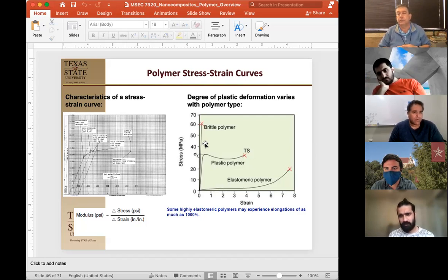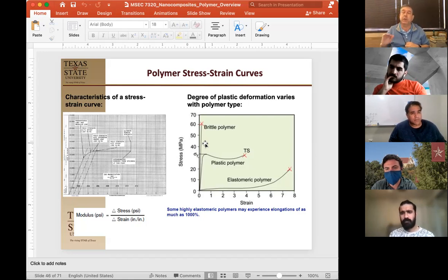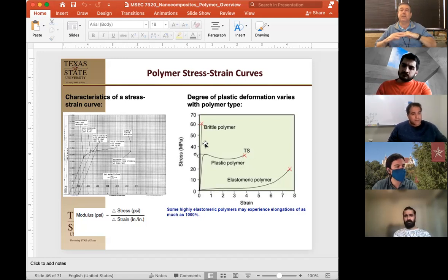Okay, so we're not looking for a failure point when you're dealing with the hardness. It's just the penetration. No, and it should be a rebounding penetration. It should not be a permanent deformation. So you put it on there and you should be able to do it multiple times and it should rebound. Okay, thank you. So it's not a failure test. It's a reproducible springback test. You don't measure springback. It just should spring back.